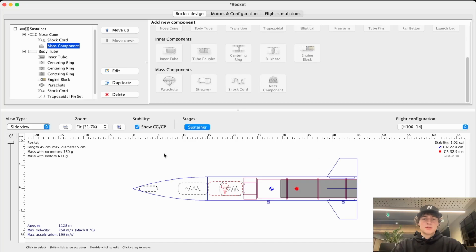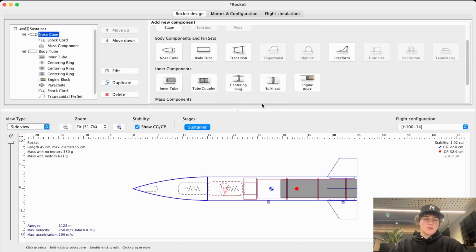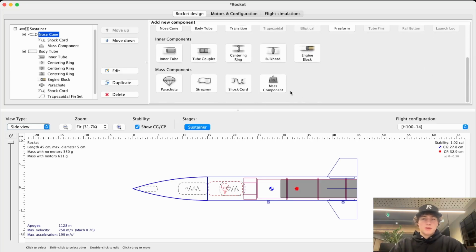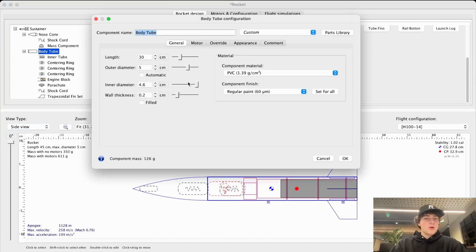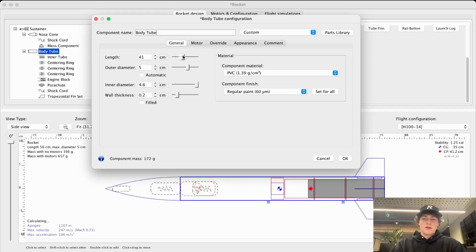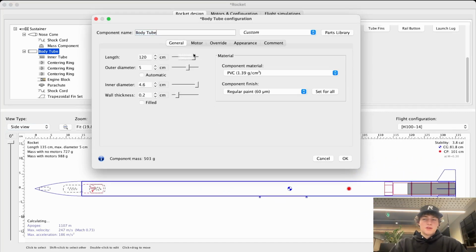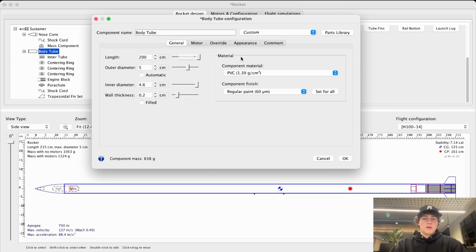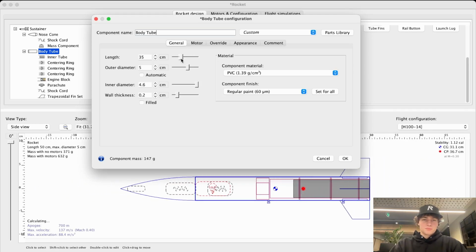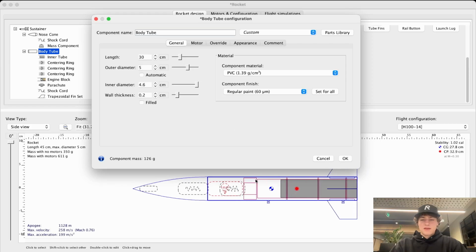All right. So we are above stability of 1, which is lovely, but I reckon we should probably get our rocket even more stable. So another way we can do that, besides adding mass, we could make our rocket longer. If I just make it longer here, you'll notice our stability getting really, really good until we're way overstable. Now, that works for a couple of reasons. Again, we're moving all this mass even further away from our CG.